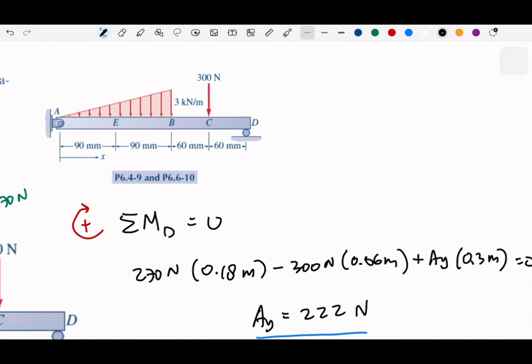So we have three sections, and then we cut, because at those intervals, we have external loads that might interfere with our graph. And usually, when this happens at the C, you will see that the point will jump. This is going down, so you have maybe a point here, and it's going down at those C points for the shear force.